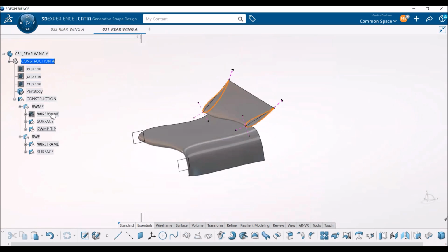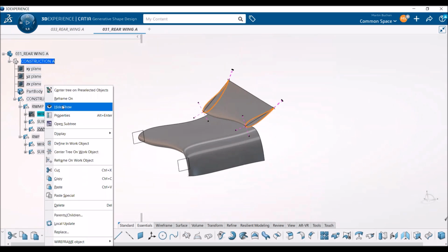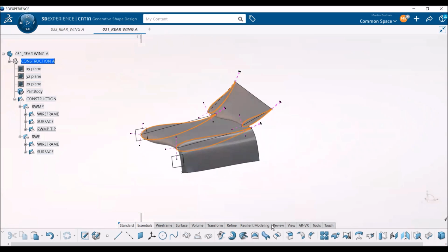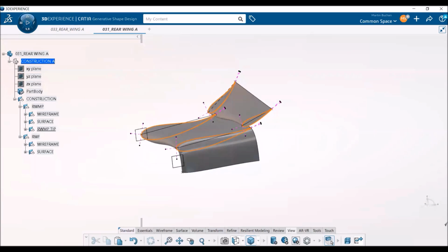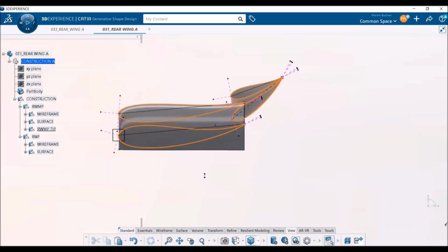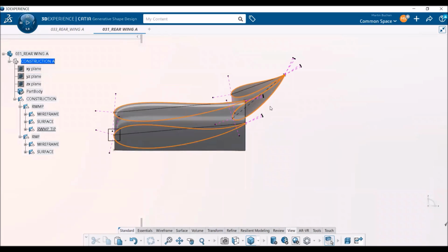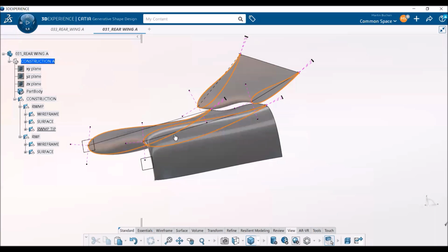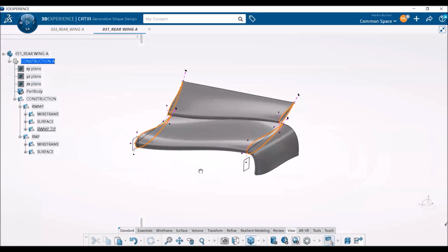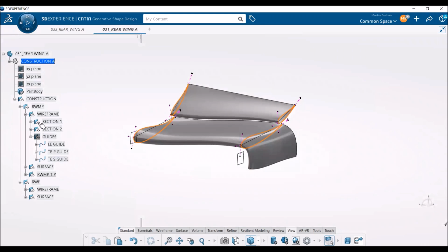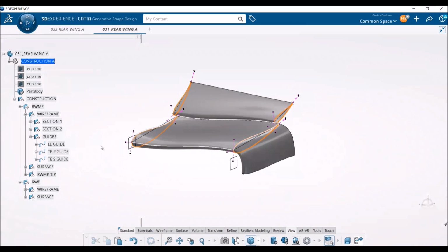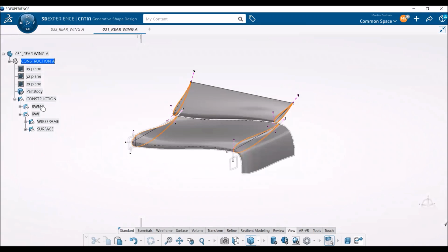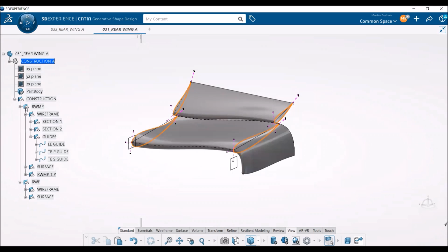If we look at the wireframe, we have our rear wing main plane in the tree and the rear wing flap below, and then each construction has a wireframe and a surface. You can see the different profiles here. So the lowest one is the center profile of the main plane, and the upper one is the flat profile of the side. You reduce the camber of the outside profile to reduce the downforce level there, so you don't have such a high pressure difference and you have less induced drag.